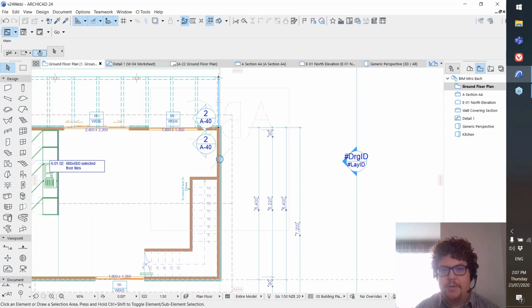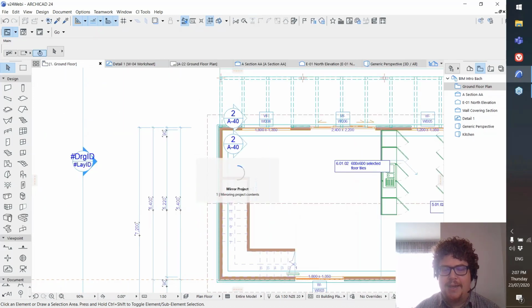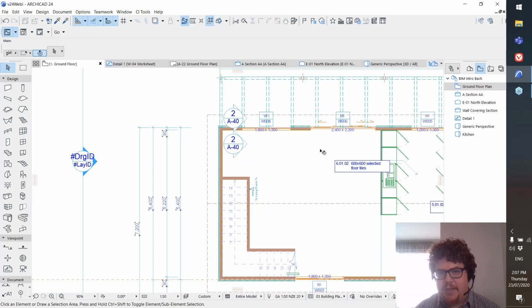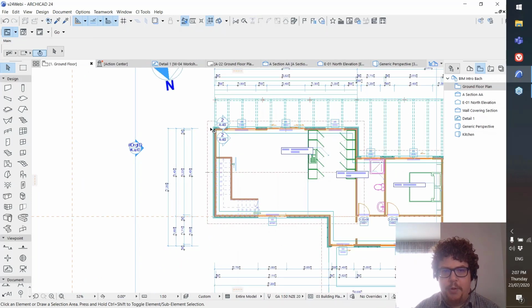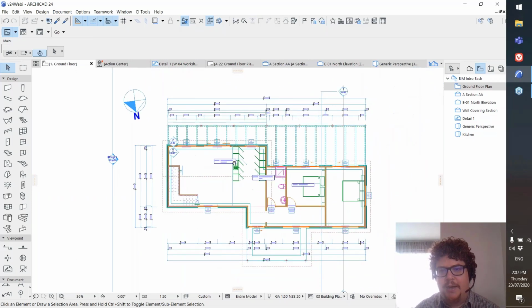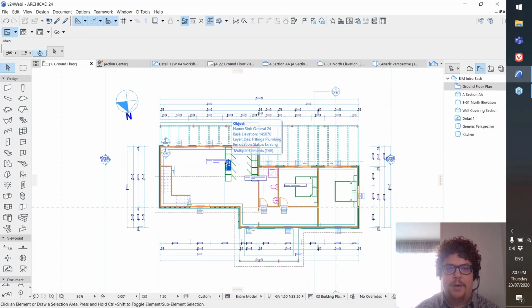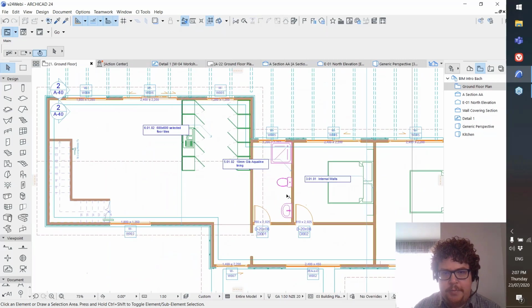So mirror it first in one axis and then come back and run the command and do it again for the vertical axis. And you can see that that's done the mirror now. And because I chose that rightmost point to mirror it about, it's shifted everything over as well as part of the mirror, because it was essentially offset. And you can see it's still done the right thing though.